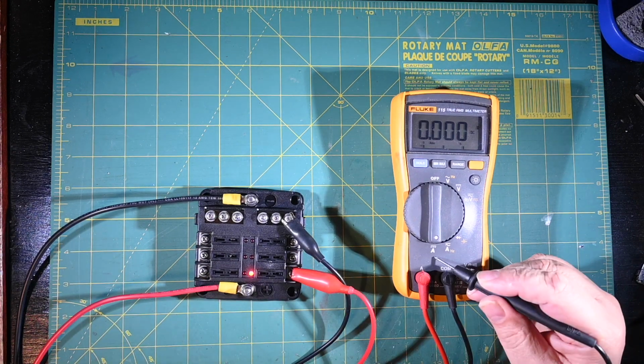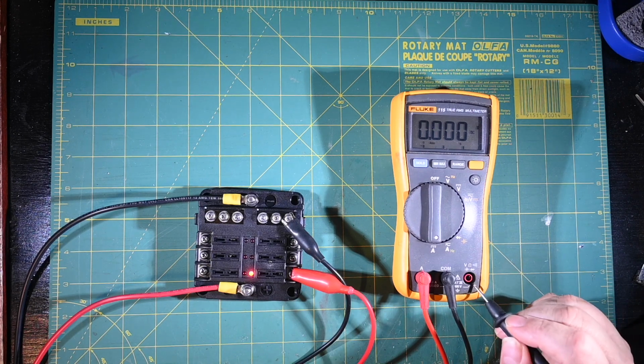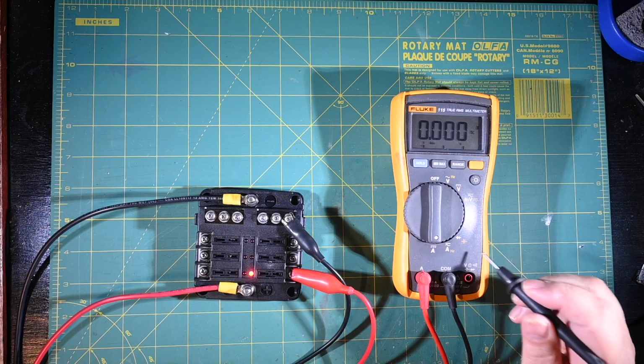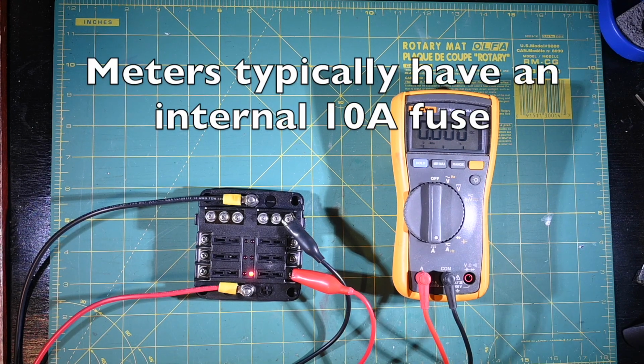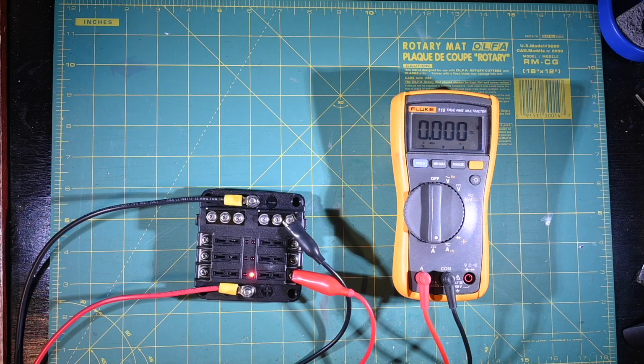And I have the meter, as you can see, in the amp scale, and I've had to move the test lead from the volt lead to the ampere lead. Now, most meters are generally designed for 10 amp loads or less, so we can get into trouble if we have more than 10 amps of current flow. However, when we're looking at standby loads, we're usually way under that.